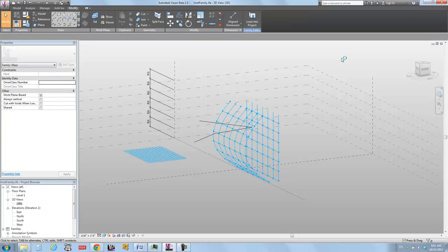So now what we've got is two different surfaces that are being sliced up using the same data. Basically what this means is that before, when we created a relationship between the interior and the exterior shell, we had this sort of weird splayed out relationship, which might be what you're going for, but most people are not going to be going for that sort of thing. You're going to want something that has an overriding system that determines how you want things connected, and you're going to want to override a UV coordinate system.